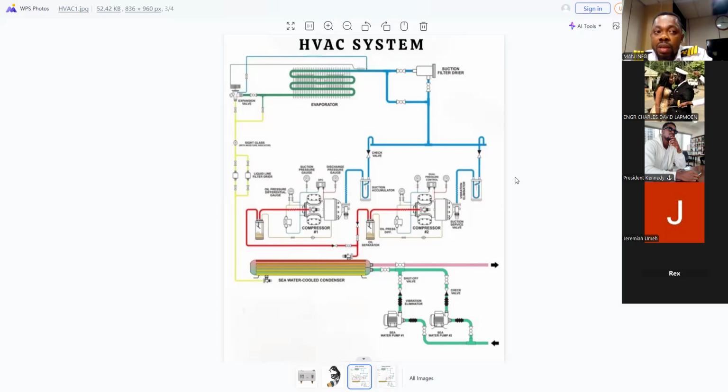The compressor always has the highest percentage. So we also recommend that any time you are replacing a compressor, you need to push out the oil that is in the system, then properly remeasure and distribute the appropriate oil to the compressor. This is really applicable to the automobile side because the oil travels with the refrigerant. But in residential, that pneumatic compressor, the oil that passes following the refrigerant is very minute.